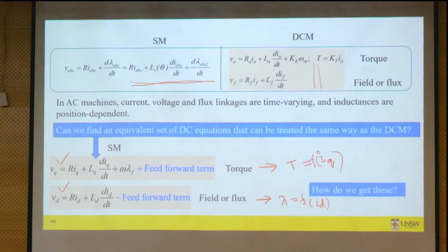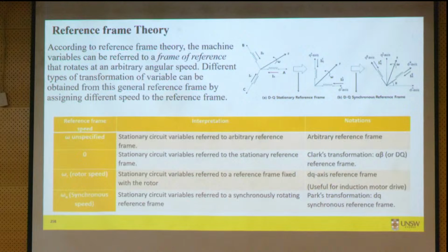So we can also get separate, or decoupled, torque and flux when we use the DQ dynamic model. That's the main reason why the reference frame theory, transformation, and DQ model are the key for achieving advanced control such as field oriented or direct torque control. I guess you have understood the reference frame theory and the transformation. It comes from the concept of rotating magnetic field.